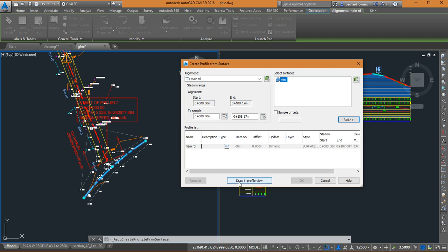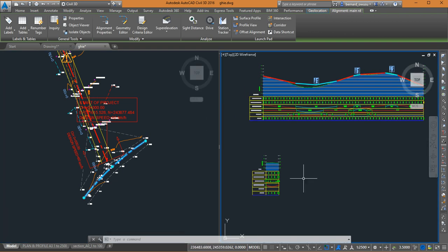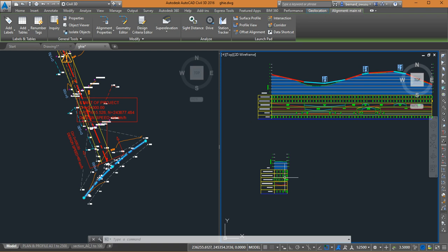If you add, you click on draw in profile view, then go next, all the way to the end, create profile view. Then you come and select where you want your profile view to be. Please, who is still behind? Successful.